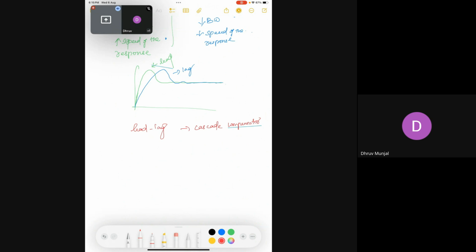So in terms of adjusting the steady state and transient response, if you want to work on both, for example, in the last lag compensator design problem, you didn't get proper gain margin and phase margin. So in that case, you would have to change both. So first focus on one thing. First focus on gain margin, design a lag compensator, and see if you get the desired specification in your transient response also, that is in terms of phase margin also. Here we got it only with the lag compensator. It pulled the phase margin from minus 4.18 degrees to 41 degrees only with the lag compensation.